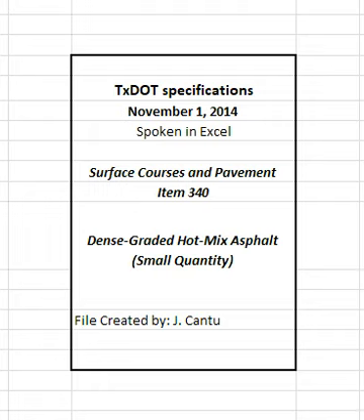Mark the cores for identification, measure, and record the untrimmed core height, and provide the information to the engineer. The engineer will witness the coring operation and measurement of the core thickness. Visually inspect each core and verify that the current paving layer is bonded to the underlying layer. Take corrective action if an adequate bond does not exist between the current and underlying layer to ensure that an adequate bond will be achieved during subsequent placement operations.